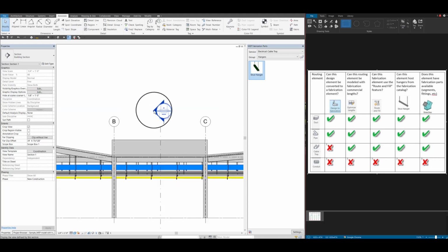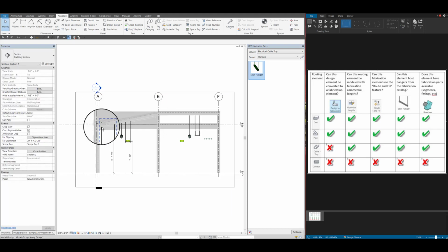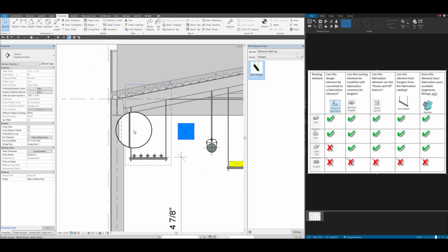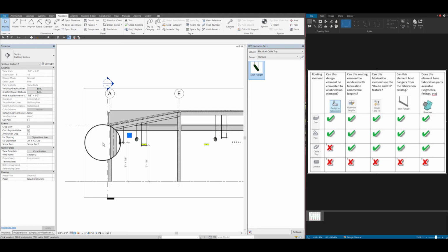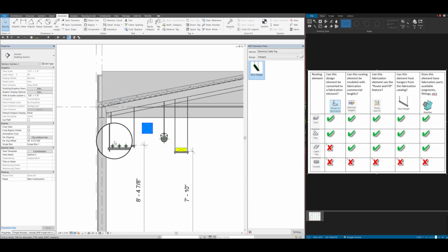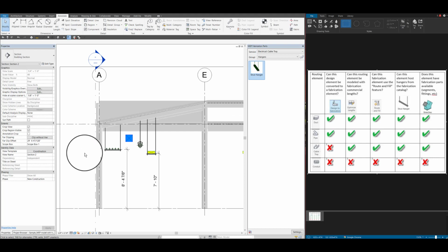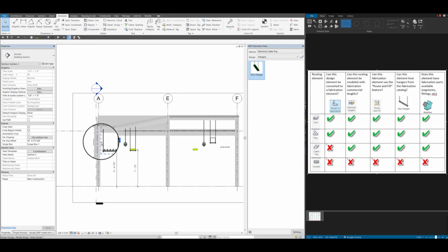If I go to the other section, notice even the two rods in the hangers for the conduits have different lengths in this case because they are attaching to this sloped steel deck. So even though they're not picking up the width of the elements, they do a good job of attaching to the structure in all the surfaces, including conduit and cable tray.